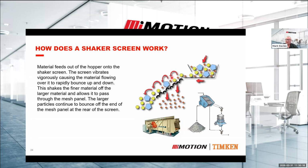It will usually be fed back into the secondary crusher, and then sent back to the screen again, so that it becomes a uniform size after a period of time. But that bouncing action of the screen forces the product to basically just walk down the screen. And commonly, screens are angled, so they're inclined to actually aid with that process.